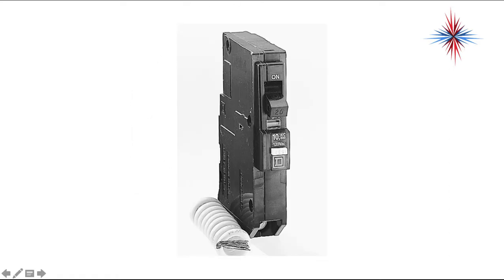This is an example of another type of breaker. This is a GFCI breaker. This will provide ground fault protection to the entire circuit. You also now are seeing these with arc fault, so that if there's an electrical spark or an arc someplace in the circuit, it will trip the breaker. In many states, they're now required per electrical code, depending on if the state has adopted the new code or not. Arc faults are required in any circuit that feeds a bedroom. Lots of times it's now any lighting circuit or any place where people are sleeping.